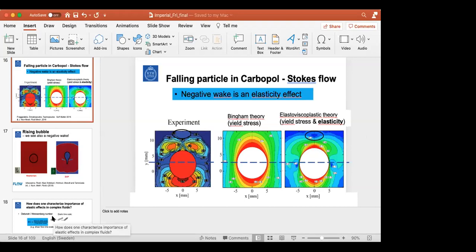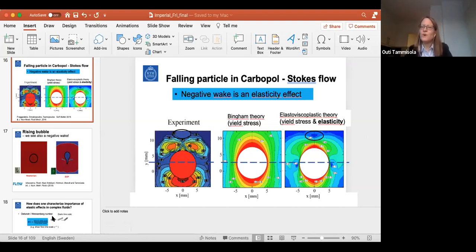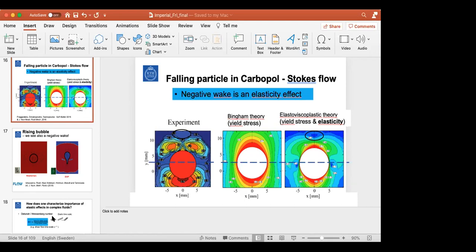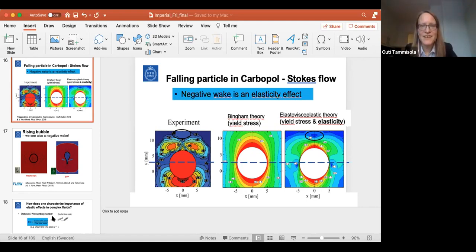So you mentioned the interface. So you are tracking all the bubbles, right? Yes. So you have multi-connected regions. Do you allow for bubbles to burst or merge? No, in this case, because it's a front tracking method. If you want the bubbles to merge or break up, then it's a little bit difficult to handle with this method, because you put all the Lagrangian points on the surface. And if you want this to be not one surface but two surfaces, you need to do something when it should break up.